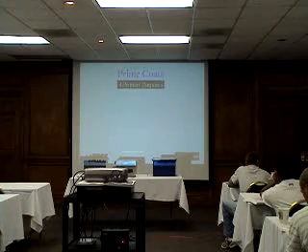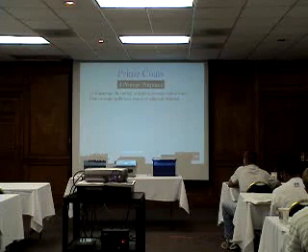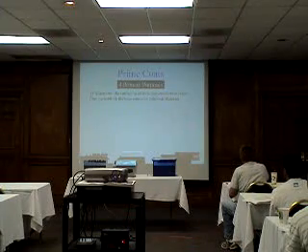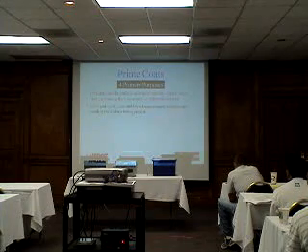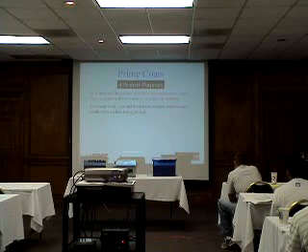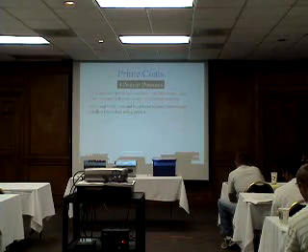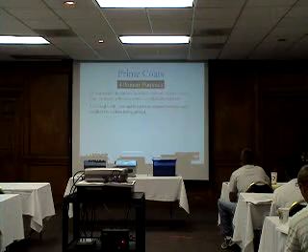Four primary purposes of a prime coat are to waterproof the surface, prevent surface water from penetrating into the base or subgrade material, seal voids, and coat and bond loose particles, stabilizing that surface that you're going to be priming. If you go out and set up ABC, what do you use to set up ABC?